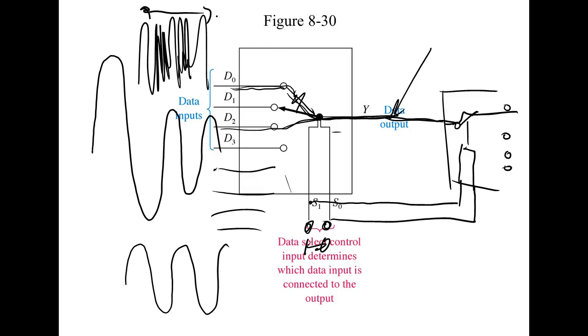And what we do, guys, is we have what we call tuned circuits where we can strip off the carrier, and then we end up with the information. If you're in AC, they'll talk a little bit about tuned circuits, where we can set up filters, and what a filter will do is strip off the carrier and let the information come through. So FM is up in the megahertz, and what you're doing, guys, is you're setting up a tuned circuit.